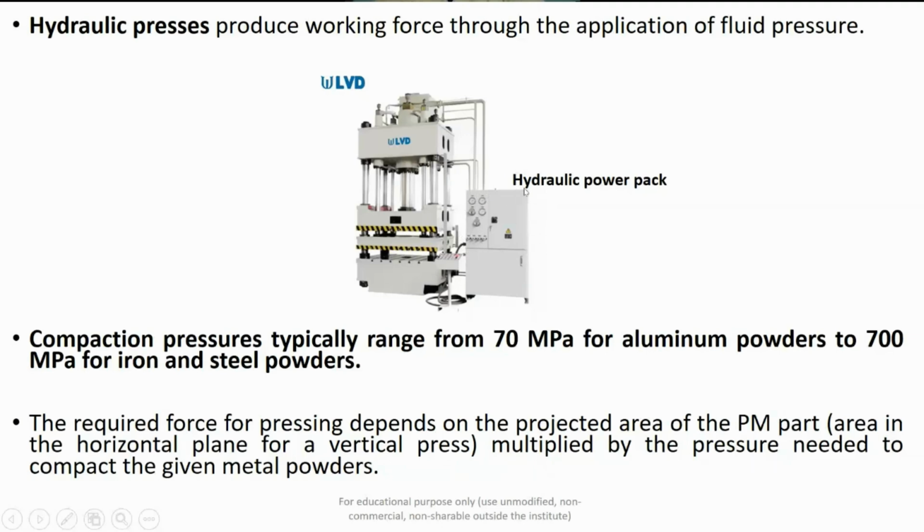In this hydraulic power pack you have a big hydraulic pump, which is used to create the necessary pressure in the hydraulic fluid, and this fluid is transferred into the top reservoir, which has the required pressure. And through this top hydraulic arrangement, the necessary pressure is applied, or transferred, to the main slide.